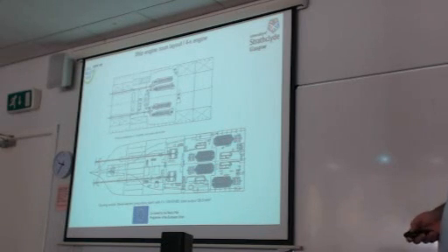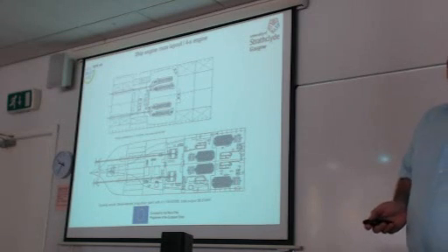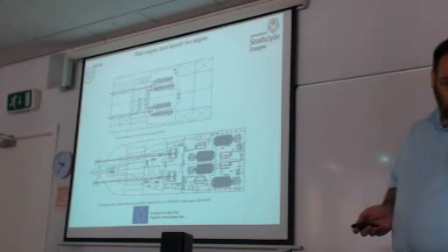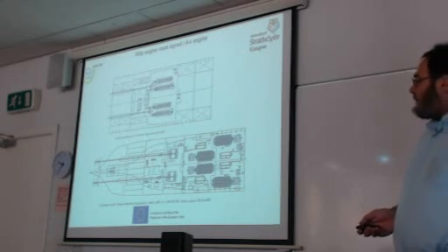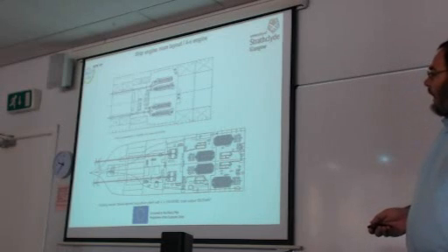And apart from the mechanical configurations described previously, there are more modern configurations for diesel electric or dual fuel electric propulsions. So in this case, diesel generator sets are installed on board for producing the electrical power, and then electric motors are used for driving the ship propellers.